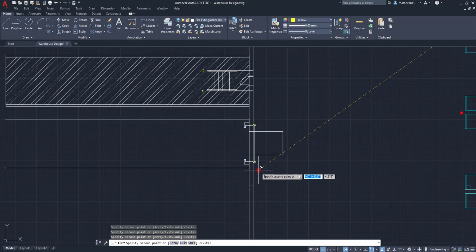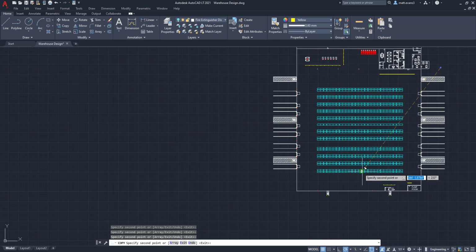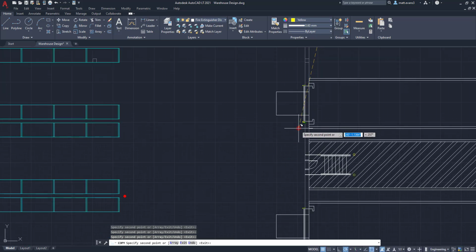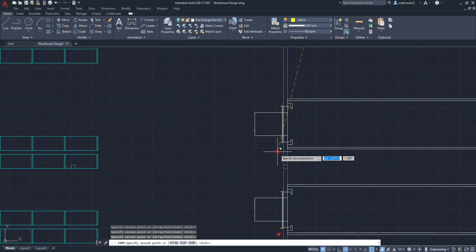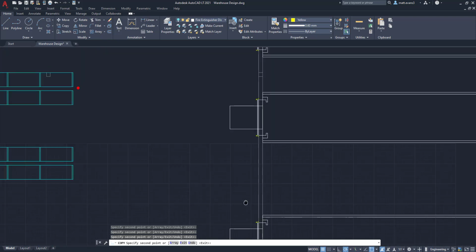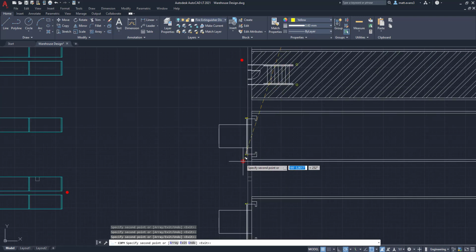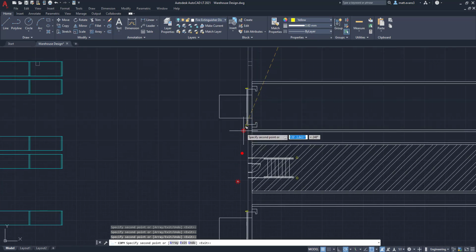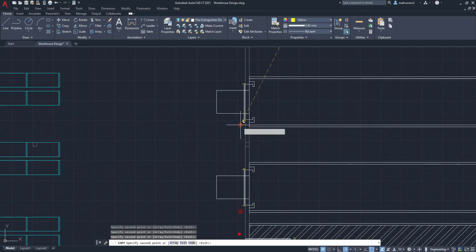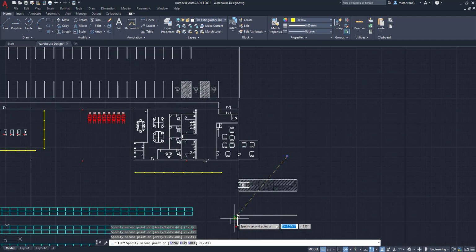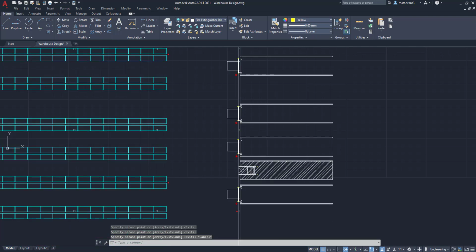Now, there are multiple different types of electric drops that you can do. Some of them are hard conduits, and some of them are essentially loose cabling that just flexes down. I'm going to see if I can pull up a picture to give you an example of each. But again, for the ones close to the wall, you always want it to come down in steel conduit and just be mounted to the wall. We're going to delete that other one right there, and we're just putting electric drops on the other side as well. So we're going to escape out of here.